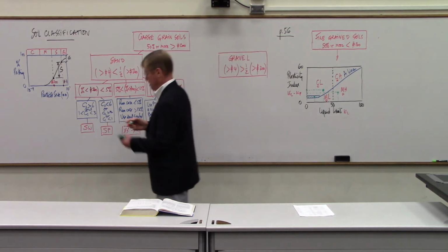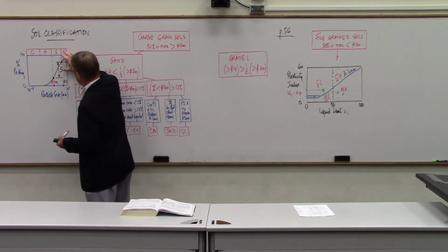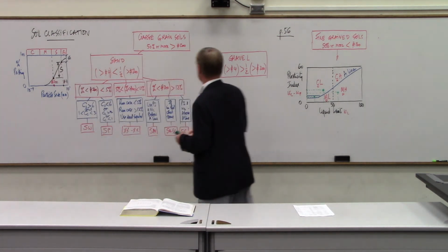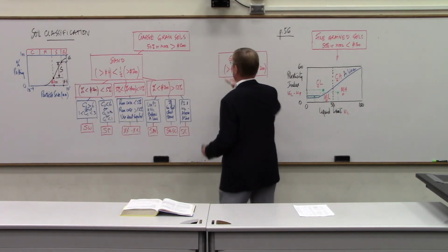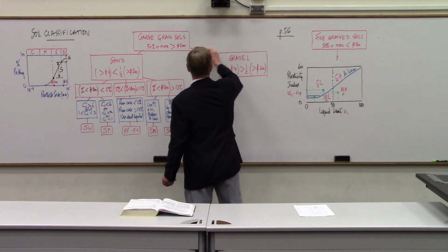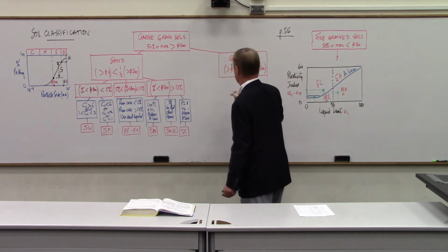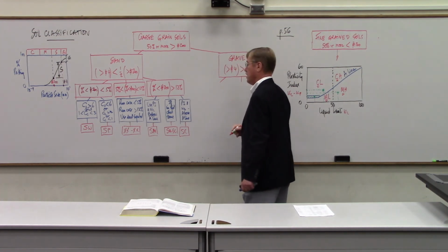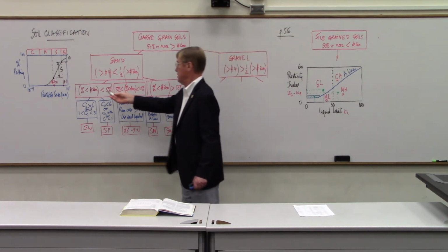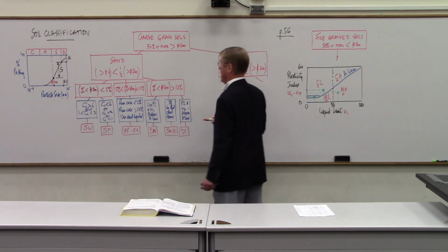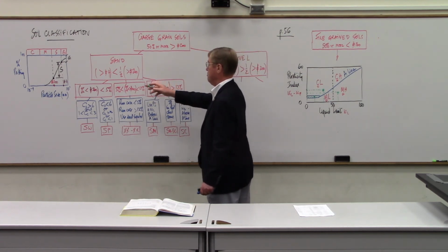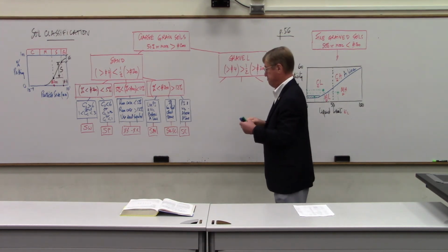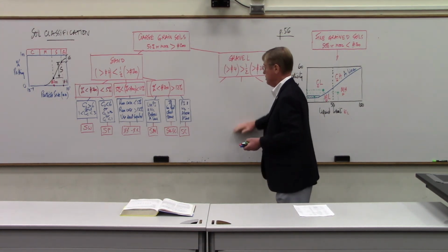Okay, but again, it would simply mean that you have a lot of gravel and a little bit of sand, so you would call the soil a gravel. And that's how it would be connected here. And then you have the 3 same boxes. These 3 boxes still apply. Less than 5%, between 5 and 12, and more than 12%. And then it would continue in there.